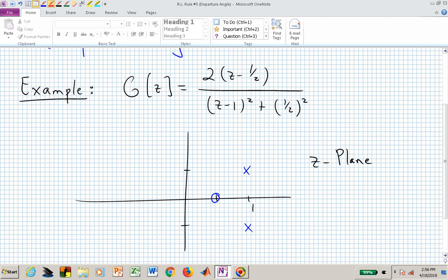We know the root loci, or the branches of the root locus, start on the poles and end on the zeros. Those zeros could be either finite zeros or infinite zeros. In this case, we have 2 poles and 1 finite zero, so their difference, 2 minus 1, gives us 1 infinite zero. We have then an asymptote angle of 180 degrees divided by that pole-zero excess, or 180 divided by 1.